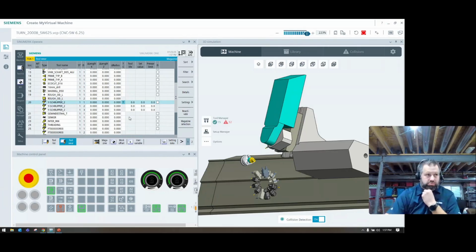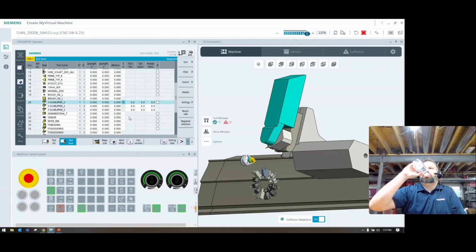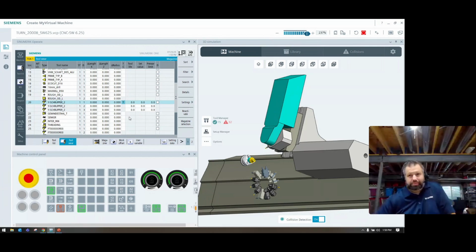Yeah. I would say the only downfall, or one of the bigger downfalls in my mind, I could envision, once you take a singular tool and a singular insert and allow it to perform as many tools, once you lose one of those cutting edges, you just lost all those tools. I think that's your drawback, right? So you could have so much more life left on the other 2 cutting edges, but I lost one because that was doing my heavy turning, and effectively that insert's no good now. Where if it was obviously unique tools, I could swap out that one tool and move on my merry way. But there's always going to be trade-offs, right, with any of this stuff.